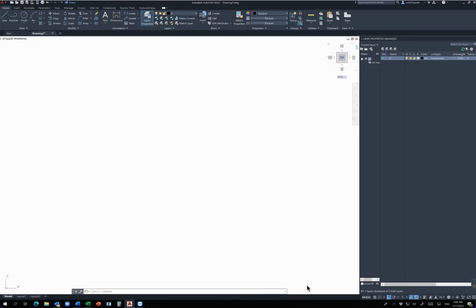Now, to start a new layer, I'm just going to click this little button at the top right here that says new layer, that has the yellow, I think it looks like a sun. This is how I see it. So I'm going to click on this new layer button right here, and you can see that once I do that, a new layer adds, and it's automatically named layer 1. Can I keep it as layer 1, 2, 3, 4, 5? Of course you can do that, but that's not recommended, because when you end up with a document that is 100 layers big, you lose track of where your objects are located. So it's always better to name them.